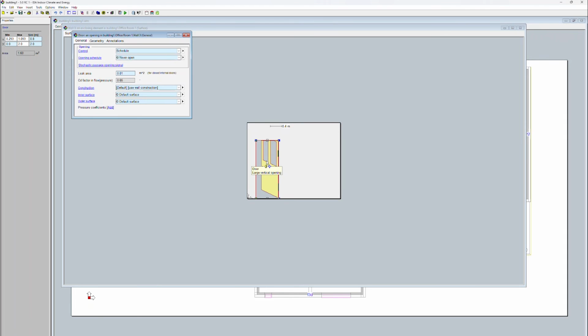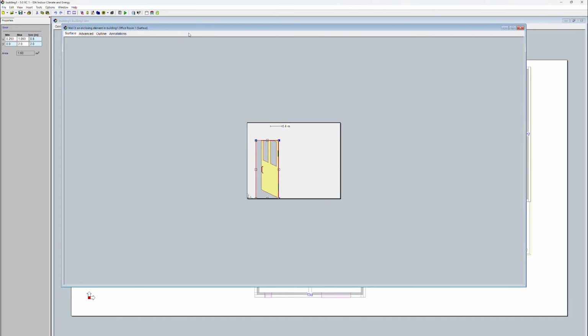When an opening is defined to be opened, bidirectional airflow through the opening can be calculated. Radiation is also considered. Also note that an opening only needs to be included once in a model. In the adjacent zone, ICE automatically includes an opening into the relevant surface.